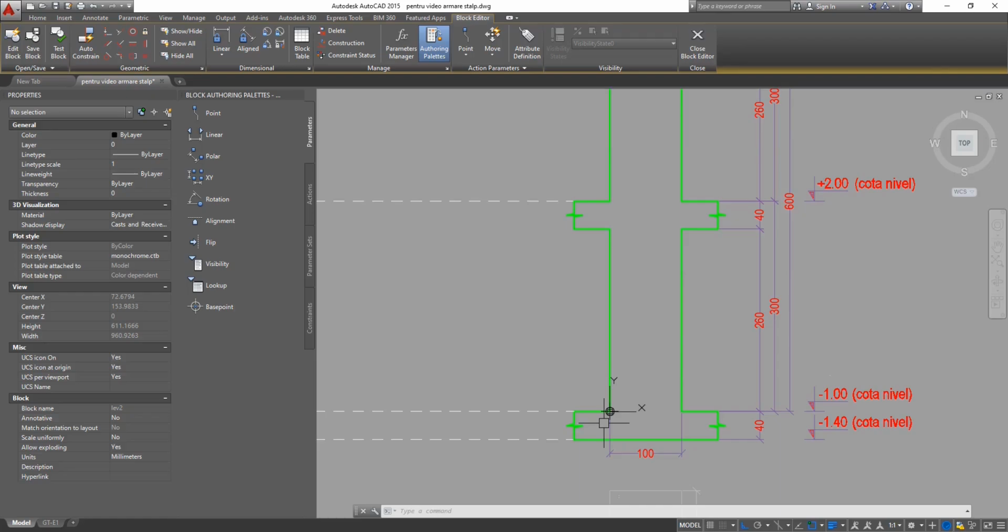The base point parameter is vital to be placed. Why? Because the future parameters, along with the Lisp, again, all the parameters will have their lengths and starting and end points taken into consideration by the Lisp command in respect with this base point.